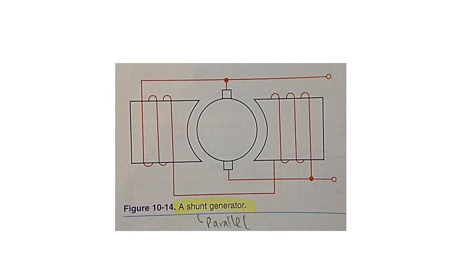Look ahead to the diagram of the shunt generator shown in Figure 10-14. A residual magnet field will cause a small voltage to be produced as the armature conductors rotate past the field poles. The small voltage produced will in turn cause the current to increase through the field poles. An increase in the field pole magnetism will cause a further increase in output voltage.